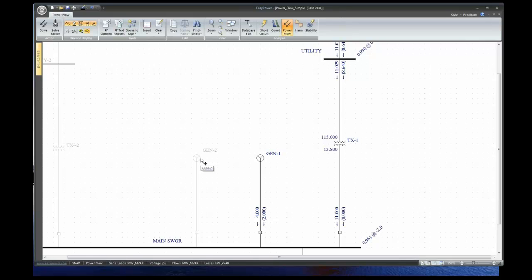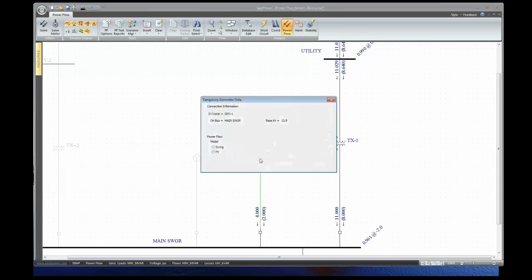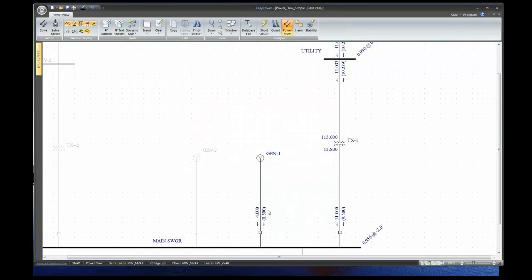All right, so if you think about it, if you have a cogeneration system at your plant, what do you get paid for? You get paid for megawatts, right? You don't really get paid for VARs. So you would like to operate really with not very many VARs. You probably want some just for stability. You don't really like to go underexcited. You're going to want to reduce that as much as possible.